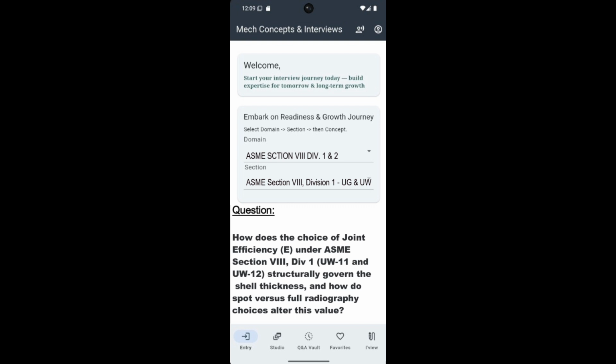Wow. Think about the physical reality of that. You saved a few $1,000s by not hiring an X-ray crew. But now your entire vessel is nearly 50% thicker. The overall weight skyrockets. Which means heavier logistics. Exactly. You now require heavier shipping transport, more robust concrete foundations at the refinery, and exponentially more welding passes to fill those much deeper 31.8 millimeter bevels.